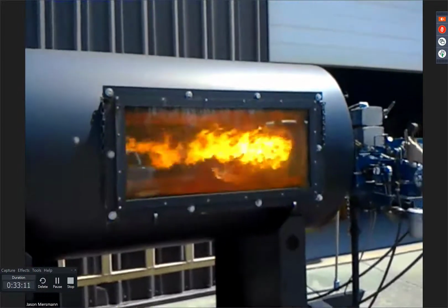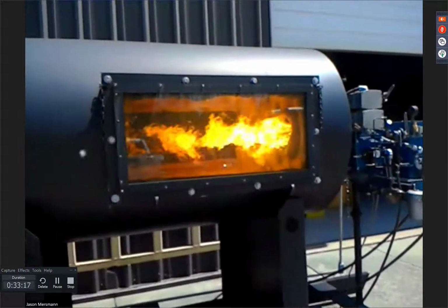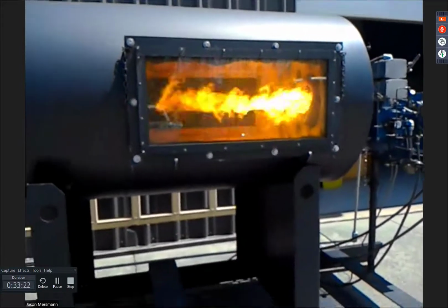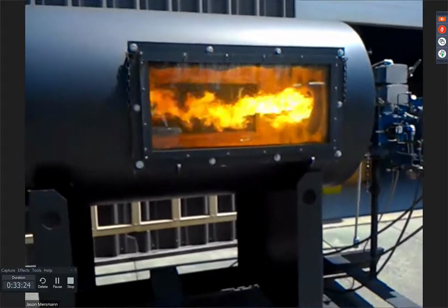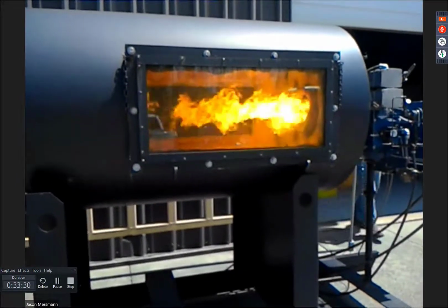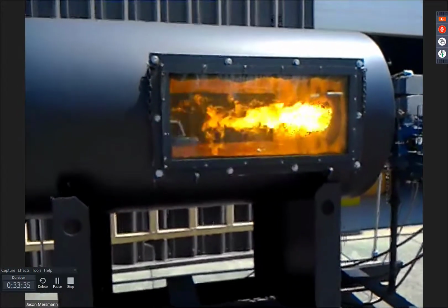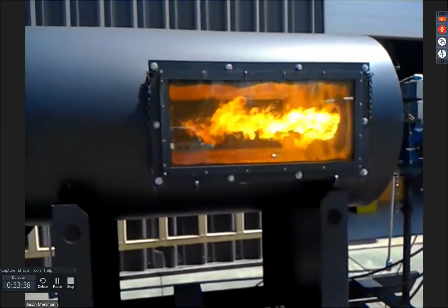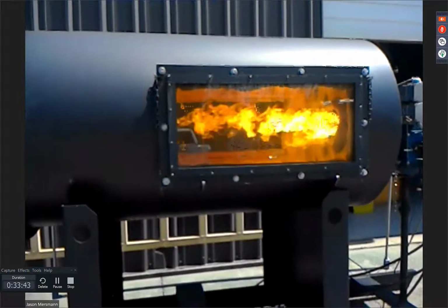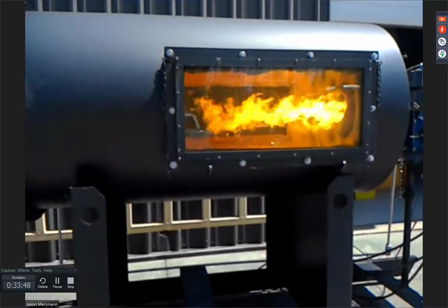So a good flame is going to be something that has a very low CO, so you have great complete combustion. On kilns, you'll have to deal more with the NOx because the temperatures are going to be high, and those are thermal NOx. I think that's exceeding 1,200, 1,500 degrees F. So that's something we've got to watch once it gets up to those temperature ranges. But on a dryer or even on a calciner, your goal is to have complete combustion, because when that happens, that gives you the most amount of heat for the input that you put in.